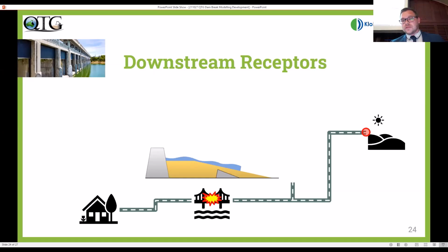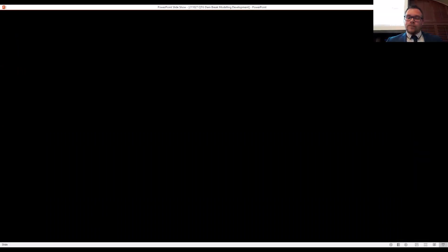What I think is the most clever part is, and ding, ding, ding, there's a theme here, it's probabilistic. It can randomise, using specified distributions, what certain parameters are for each PAR point. So not all PAR will take the same route. Not all PAR will react and respond in the same way at the same time. Not all PAR have the same physical ability and survivability. And so the modelling method, I think, provides the closest proxy we have to account for an individual's behaviour and response during an extreme event.